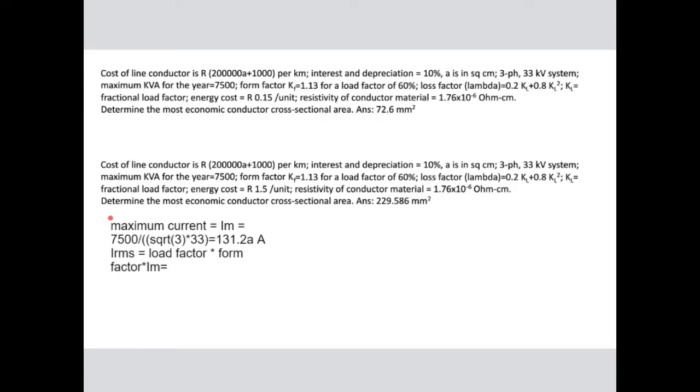Load factor is 60%, so it's 0.6 times form factor is given as 1.13, and the current that we got, 131.21 ampere.